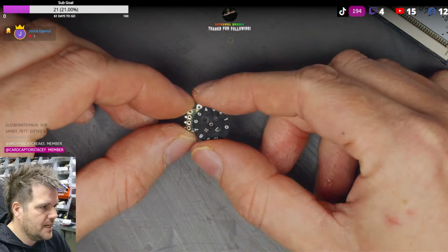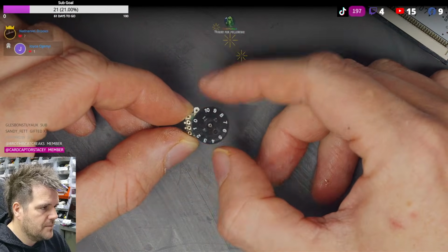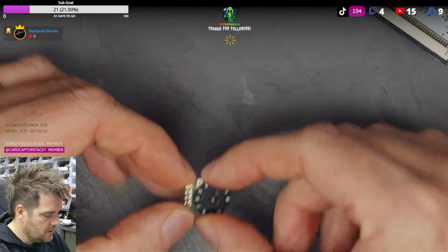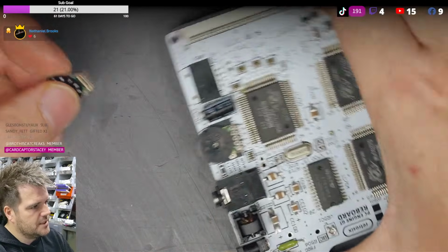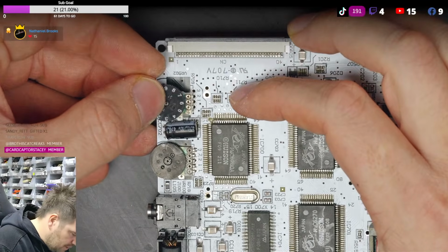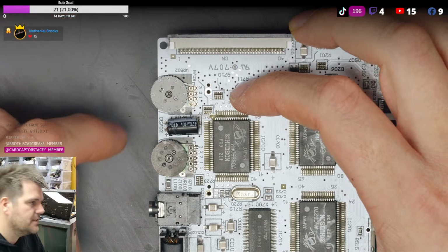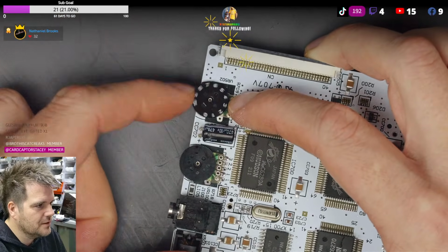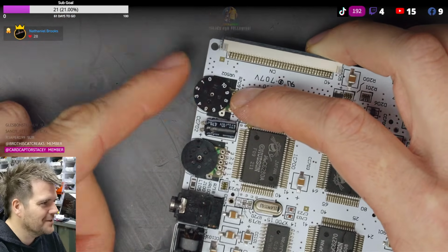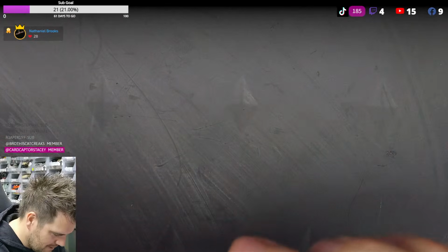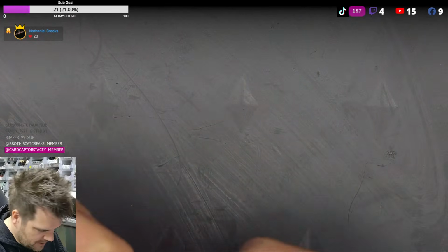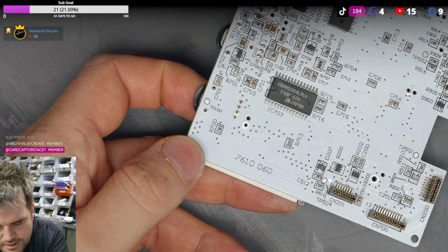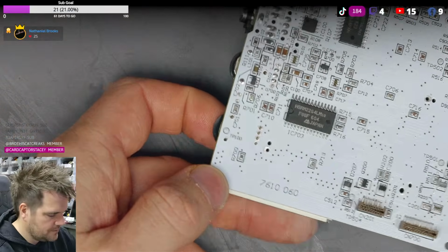But this looks very much like the exact pinout and the exact value. And we've even got dials on for the volume level. So this is going to replace the one here. And hopefully, I genuinely haven't tried this yet. Yes, fits in perfect. That slides in, and the customer's now got a volume dial. So it's going to tell him how loud the audio is. Like I say, I don't know whether that's going to be a good thing for him or whether he won't like it, but that's in. So I'll hold that down, get some solder and tack this in.